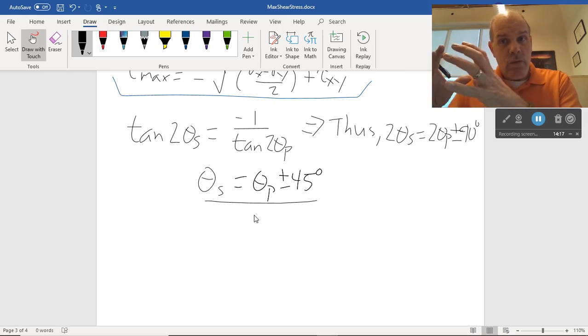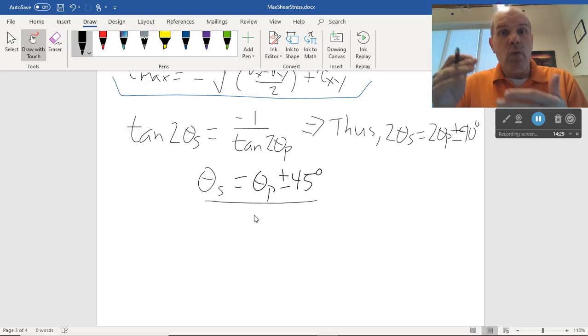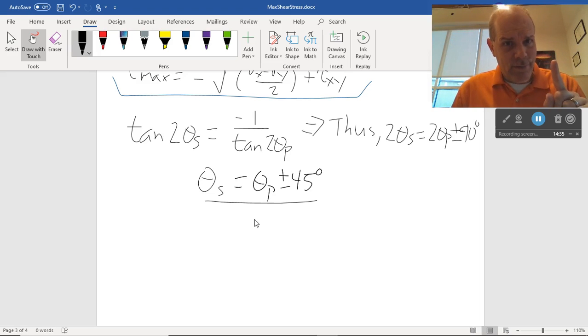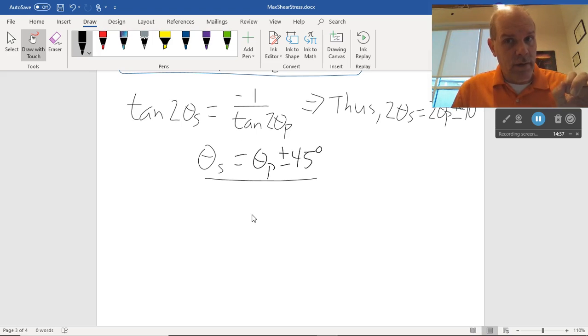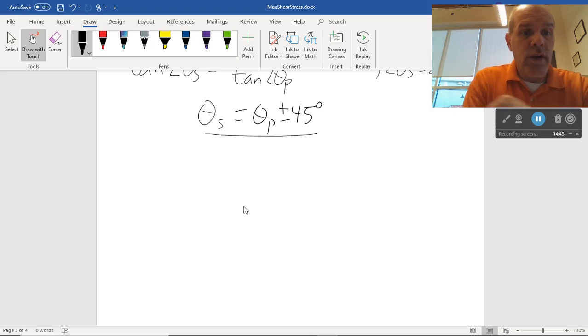When we did the principal stresses, we knew full well that the shear stress had to be 0 because the shear stress was the first derivative of the normal stress, and therefore we had maximum and minimum when the shear stress was 0. What's my axial stress now? It's not necessarily going to be 0. Okay? There are cases where it is, but those are special, right? In this case, we're going to have to look at what those stresses are.